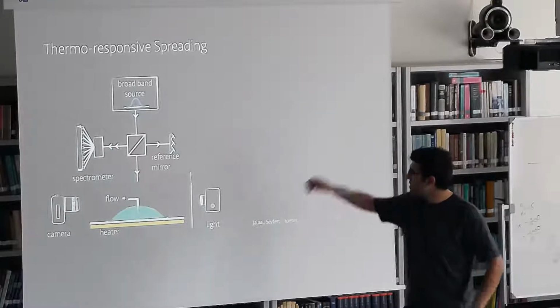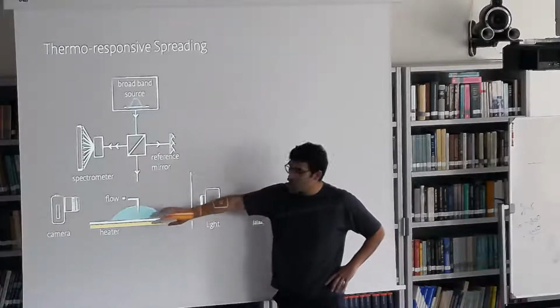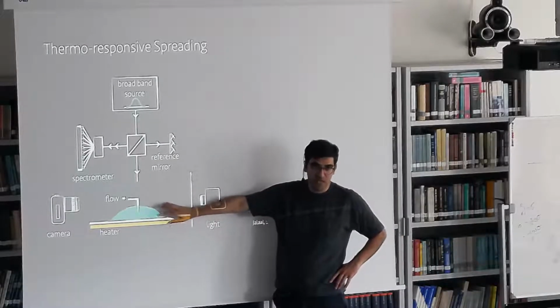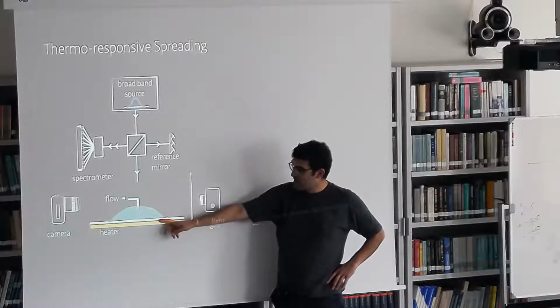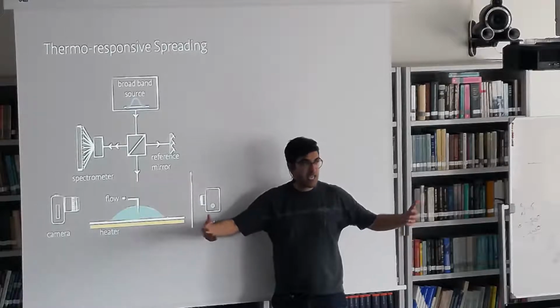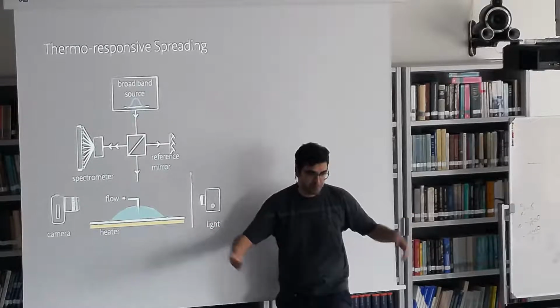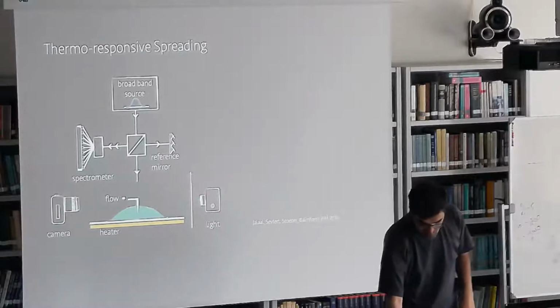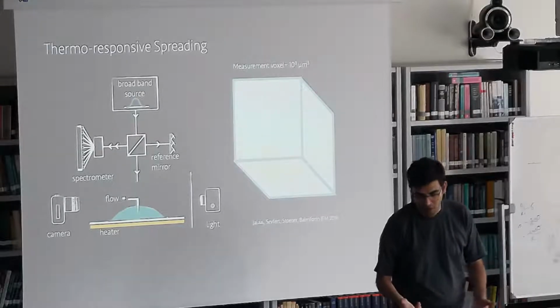So the way I use optical coherence tomography is that I want to get information from inside the droplet. So this now connects with the solidification problem that many of you are working on here. So the idea is that the liquid is Newtonian spreading. I heat it up, and can I see where it solidifies or become a viscoplastic materials, in fact. So we tweaked the method a little bit, so we went to somehow do some sort of micro-rheology with it.